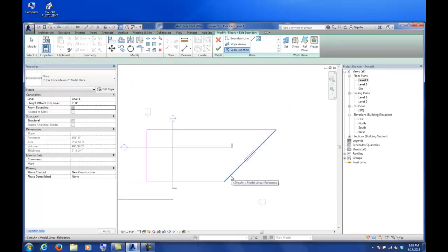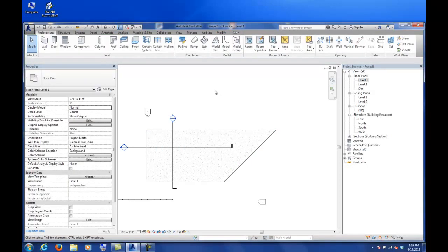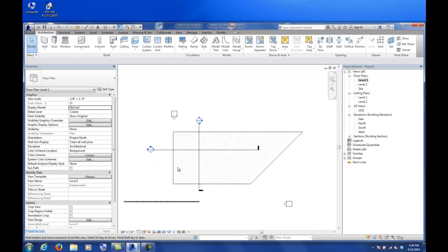If it doesn't have that in the boundary, you're not going to be able to control the span direction. Because our floor plates are very odd polygons, but our beams and columns are on a grid. So would I potentially have, and I can't remember to be honest, I suspect that most of our floor boundaries do not have an edge that is going in the span direction.